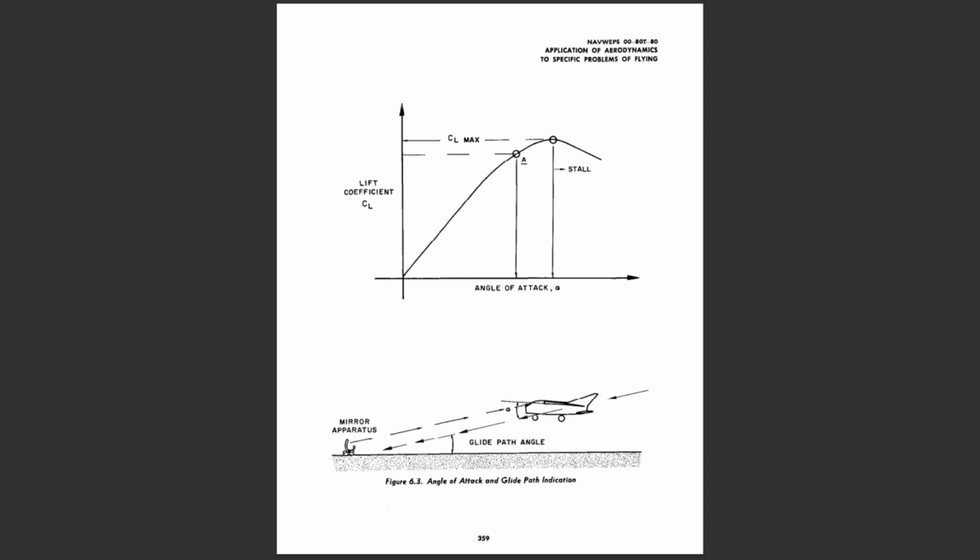In order to reduce takeoff and landing distances and minimize arresting loads, takeoff and landing will be accomplished at minimum practical speeds. The takeoff and landing speeds must provide sufficient margin above the stall speed, or minimum control speed, and are usually specified at some fixed percentages of the stall speed. As such, takeoff, approach, and landing will be accomplished at specific values of lift coefficient and, thus, particular angles of attack. For example, assume that point A on the lift curve is defined as the proper aerodynamic condition for the landing approach. This condition exists as a particular lift coefficient and angle of attack for a specific aerodynamic configuration.